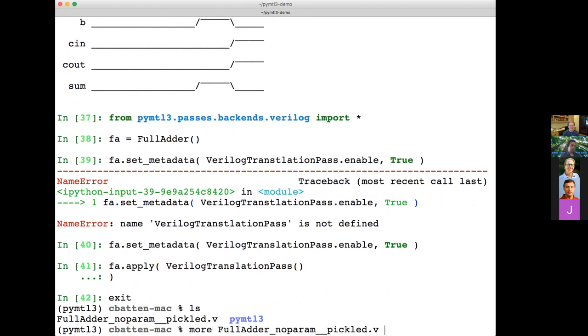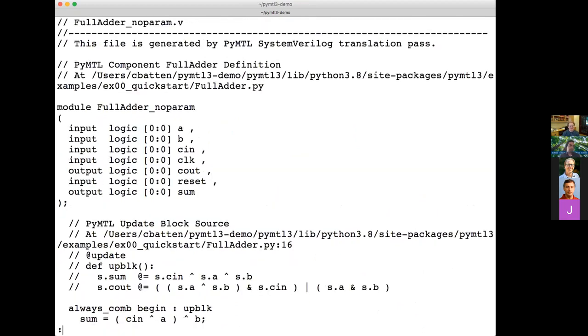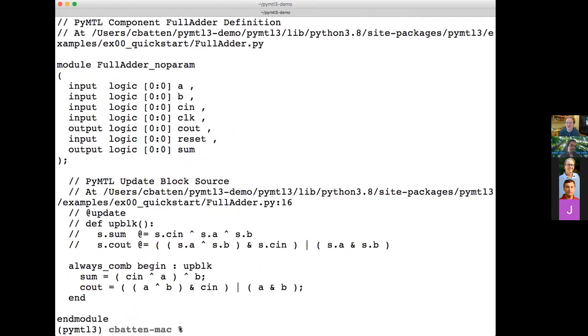Nothing against Chisel, but you're going to love it. Oh, look how beautiful that is. It's so readable. I mean, partly it's readable because we're writing at a lower level of abstraction. That's one thing that's going on here. One cute thing we do is in a comment here, we put the PyMTL 3 code, which goes along with the hardware. So you can see that direct one-to-one connection. It's basically what you would expect. So if you're used to certain Verilog patterns and such, there's a nice one-to-one mapping.